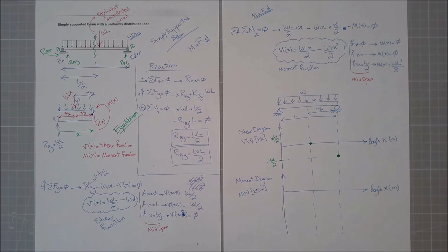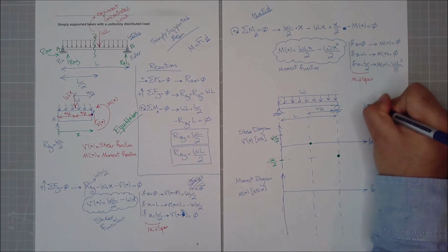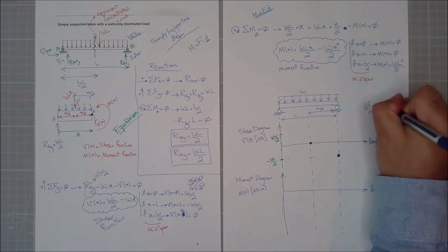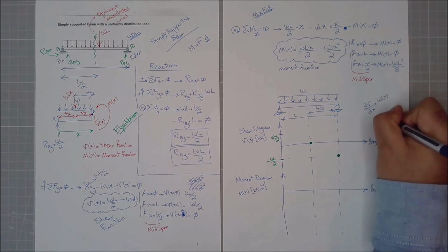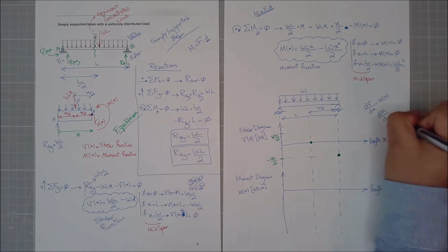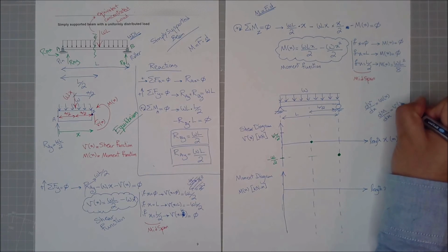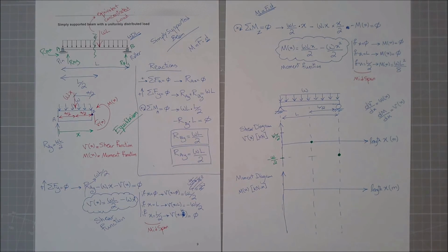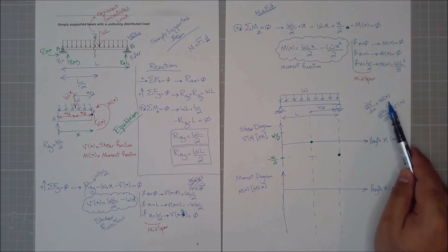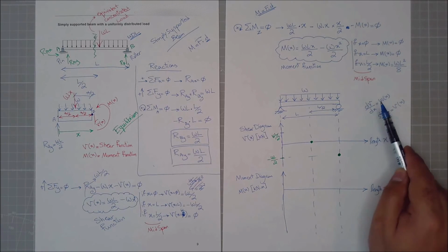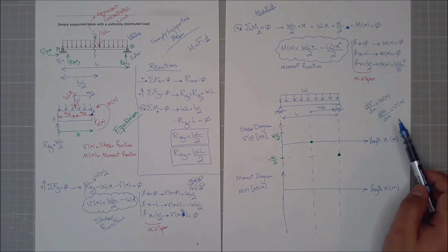Now, do you remember we had these formulations of dV/dx equal to w(x), and dM/dx equal to V(x). So always the shear was a higher order than the applied load, and the moment was a higher order than the shear load.